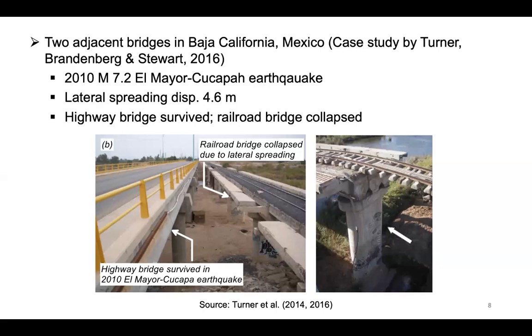When you have liquefaction issues in projects, the first approach would be trying to see if you can design the piles to be able to sustain that load, similar to the bridge example on the left side.